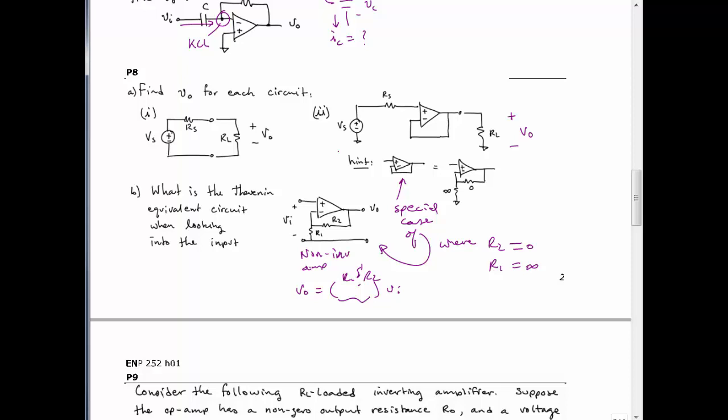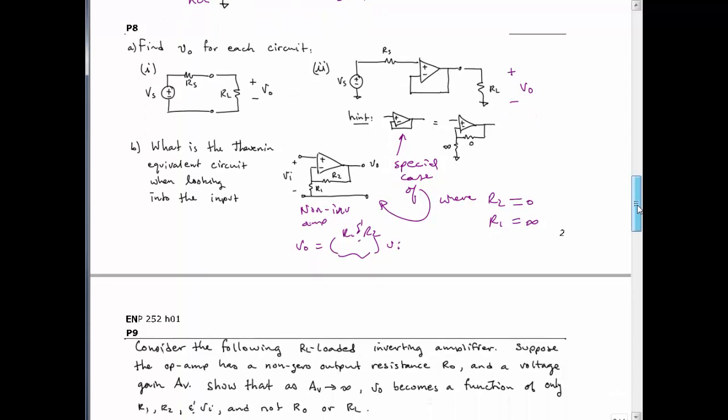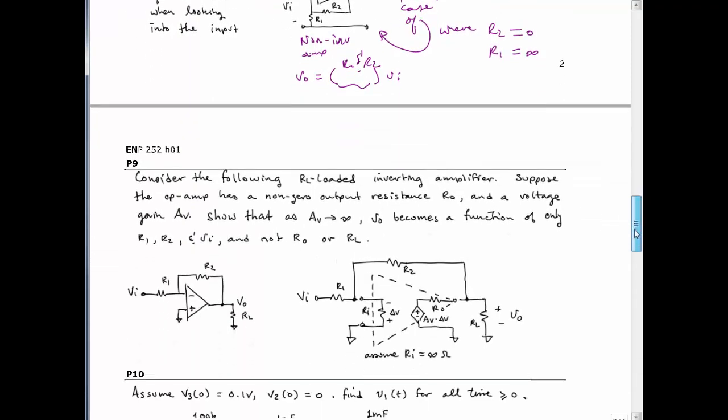So the op-amp can help us overcome the inherent voltage attenuation, particularly when our load is less than RS and maybe significantly less than RS. Right? If I had 1 ohm for R load and I had 100 ohms for RS, that would be a bad situation. My attenuation would be close to 1/100th. It would be 1 over 101. So I would not receive much of the VS that I started with. The op-amp can help to alleviate that issue.